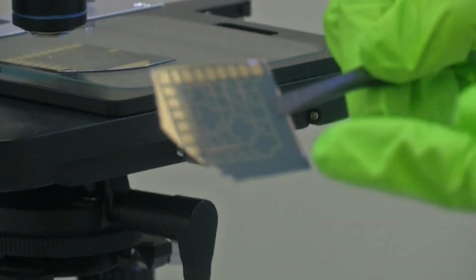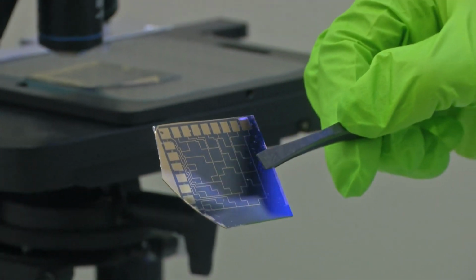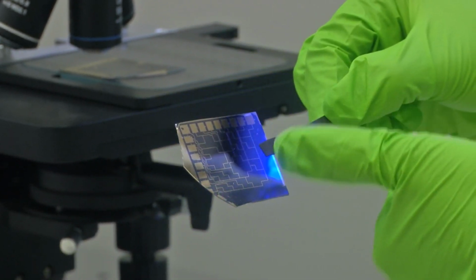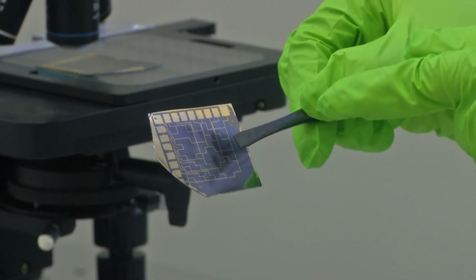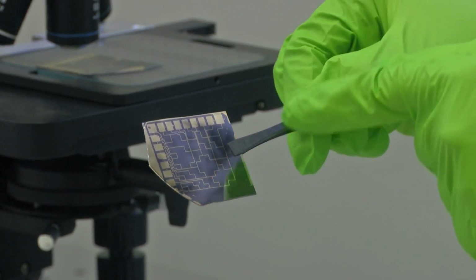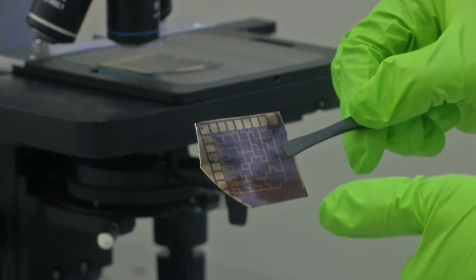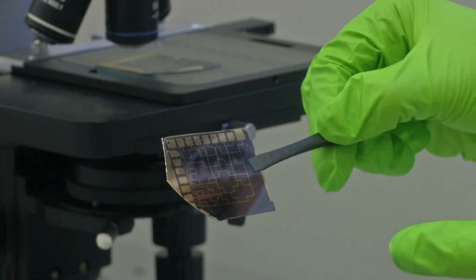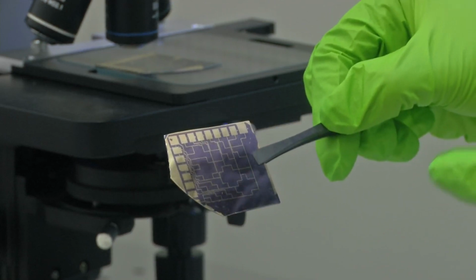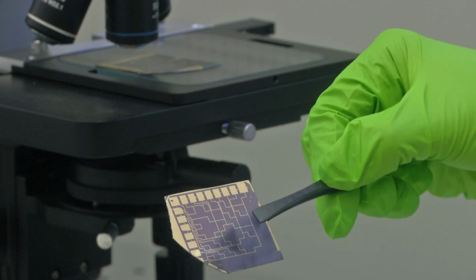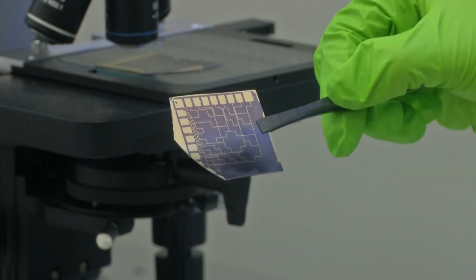If you can see, each of these are electrode pads which could be seen, I mean they can be visualized just through the naked eyes, and the fine lines which are coming out of these electrode pads are the extension, the connections to each of these electrode pads, and then there are interdigitated electrodes. The details for sure has been covered by Professor Hardik. I am sure the electrodes which are on this wafer are 50 nanometer dimension, and these minute structures cannot be seen through the naked eyes.